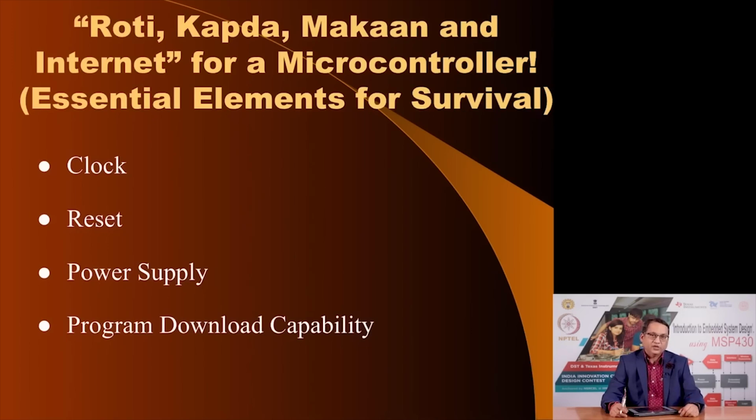And what are these four things for its survival and active working? It requires a clock. We will see why it requires a clock. It requires a reset circuitry. Usually that reset circuitry is integrated in the microcontroller itself. It also requires a power supply, perhaps different from the power supply requirement of the rest of the embedded system application.